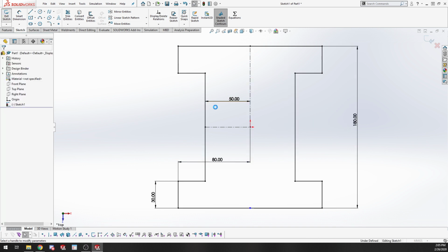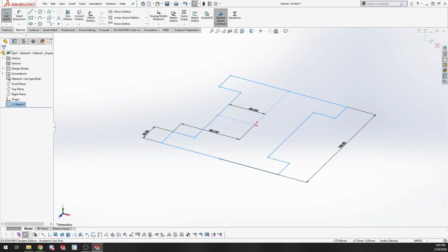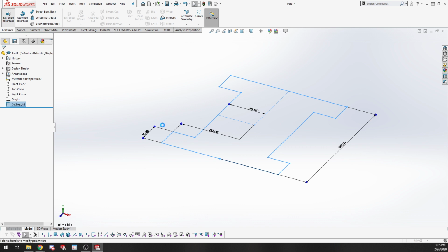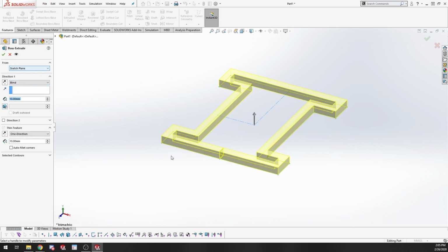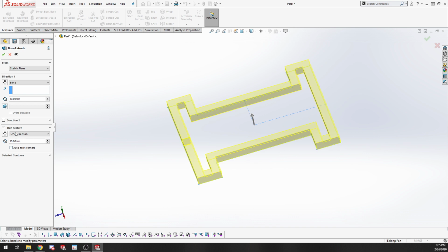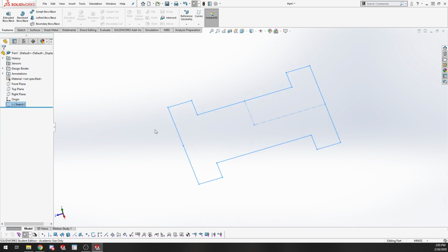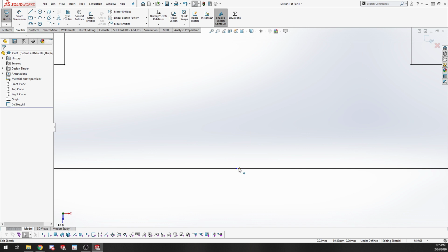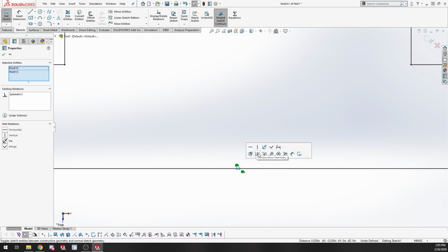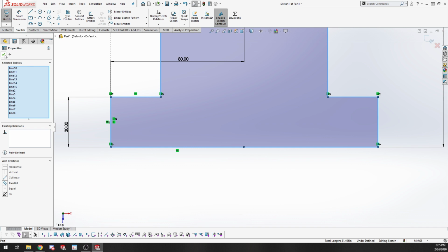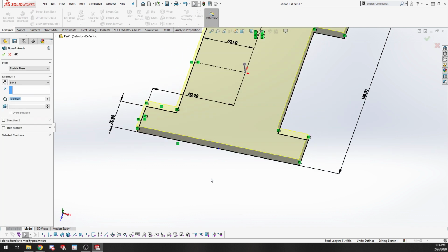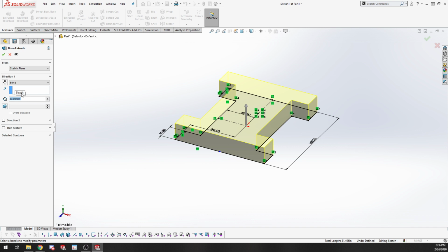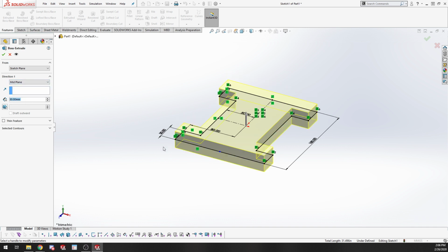All right, easy. Cool. From here, I will go ahead and just do an extrude boss from sketch plane. Not a thin feature. It's these 2 points. There we go. All right, so now I can extrude this feature out. Start with a 30 millimeter mid-plane extrusion.